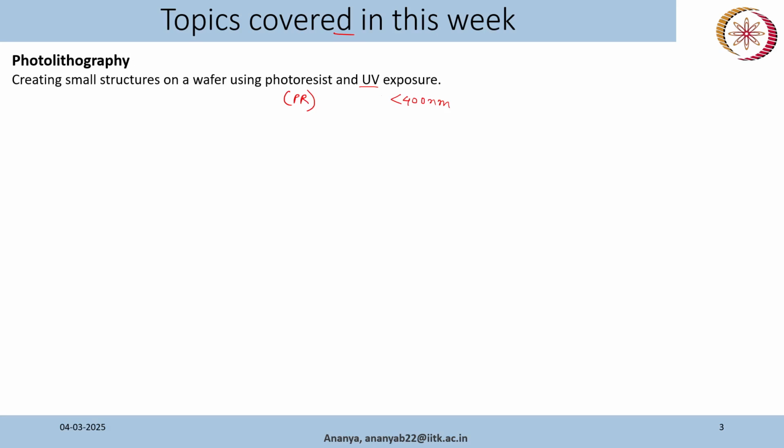So this is also something I discussed earlier, how we make a sensor. The fabrication process involves different steps, like deposition. So deposition will be uniform deposition, right? After that you want to make some pattern. For patterning, what processes do you use? You use photolithography as well as etching. So photolithography plus etching will give you patterning.